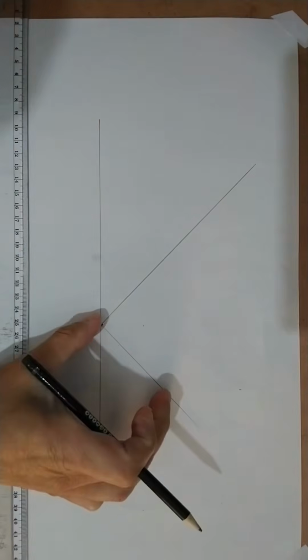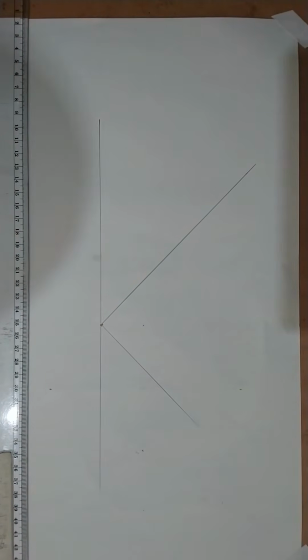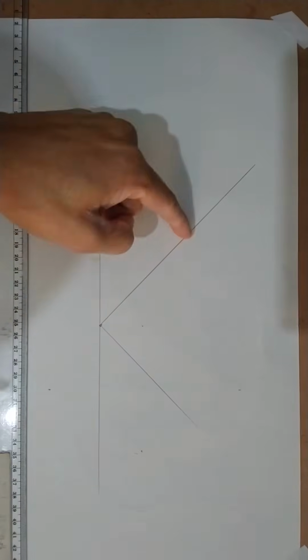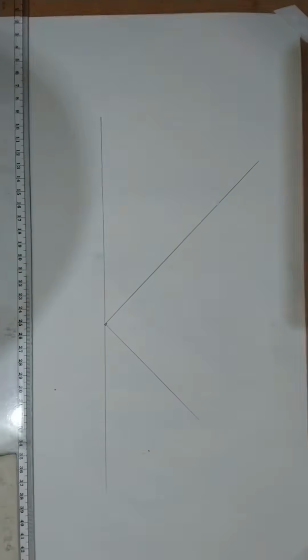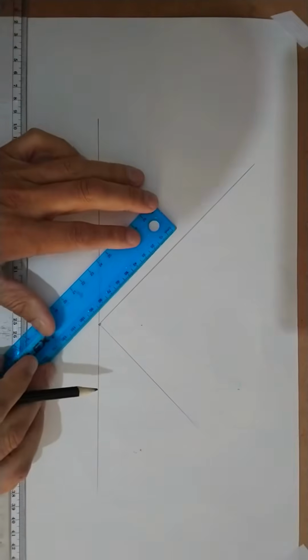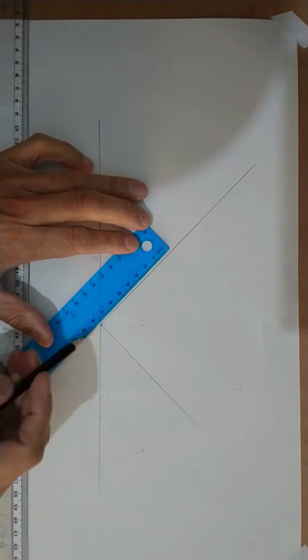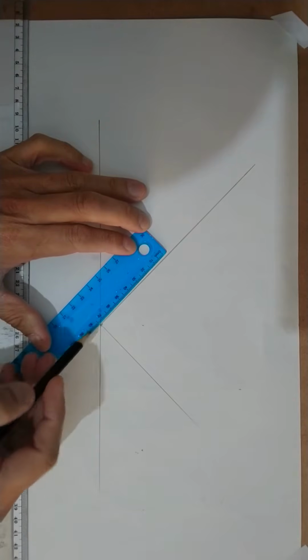They don't give you that specific size because you have to work it out with your auxiliary view. Alright, so you will be able to get your length in first, which is your 75. So I'm going to measure 75 from the point that it tilts. So 75 is going to be around about there.